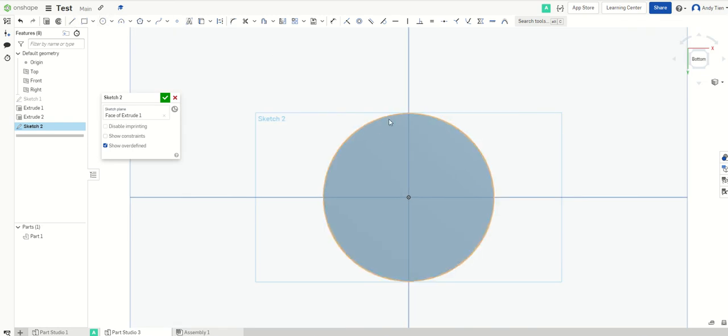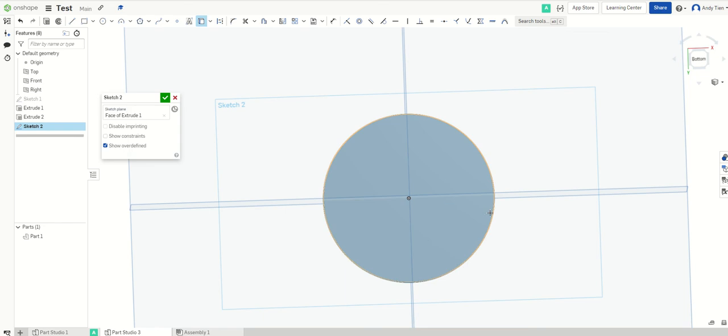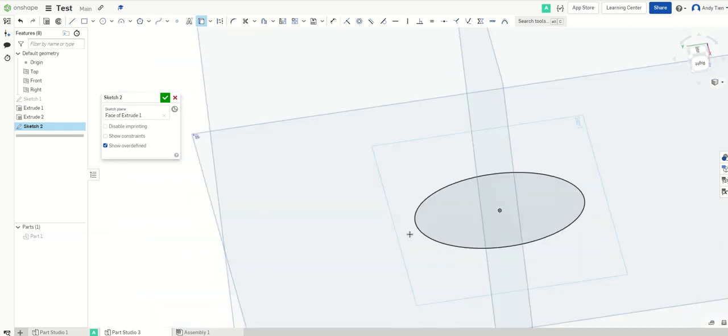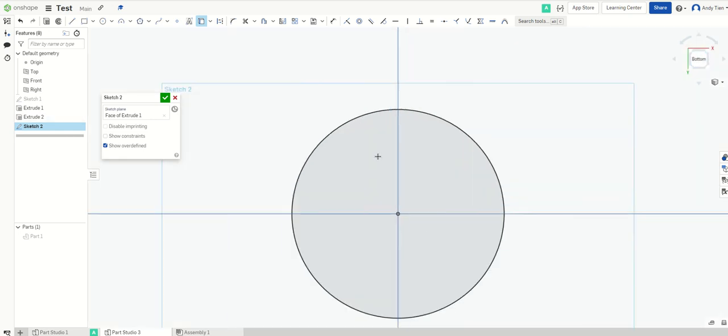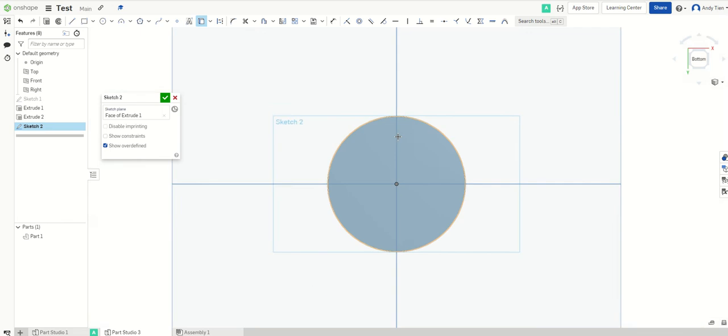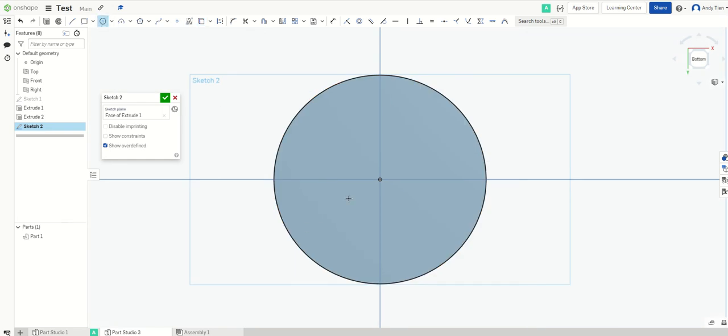We're going to first, I want to use this little circle here as one of my references. So in order to get that in the sketch, we're going to use this function called project, and as you can see, this thing now has a little thing. So if I hide this part, you can see this sketch still exists with this little part on it. So if I unhide the part and keep working, I'm gonna just create the tab with a little circle rather than an arc.